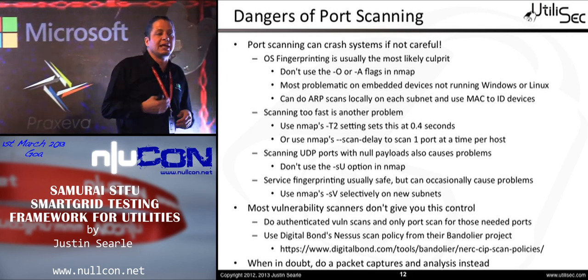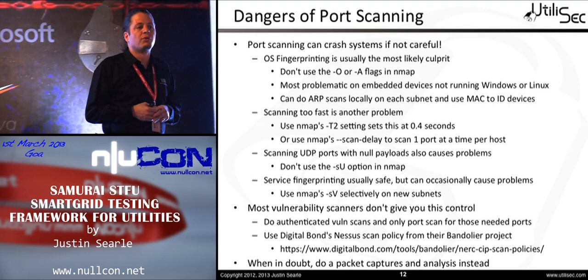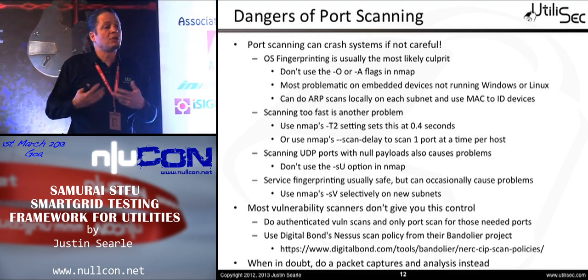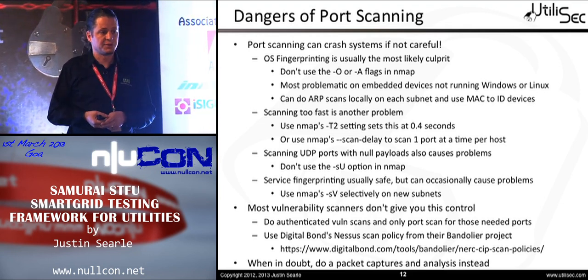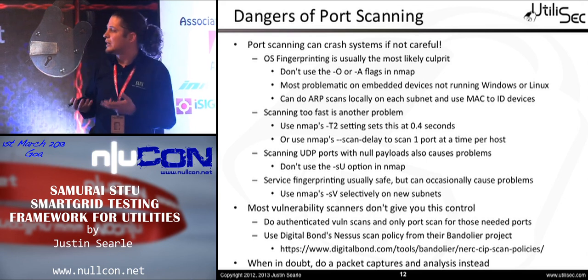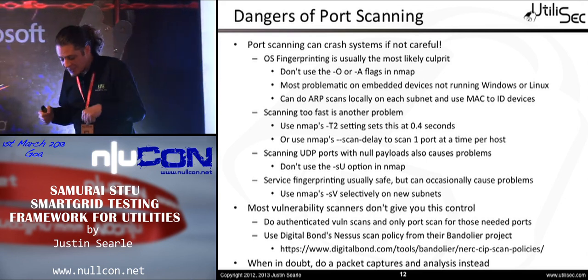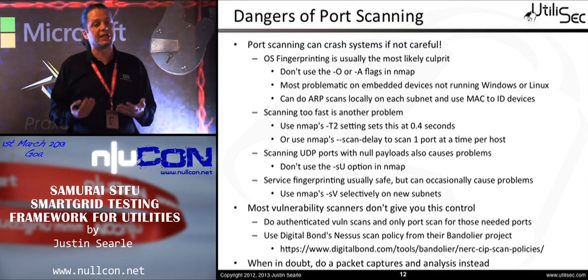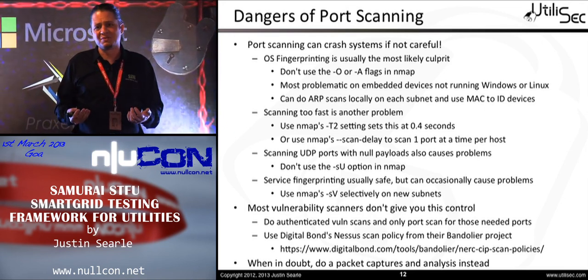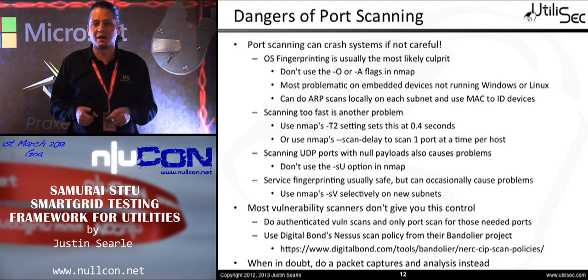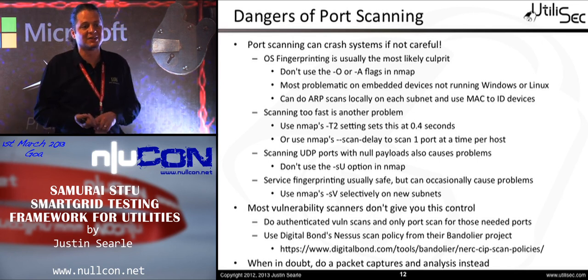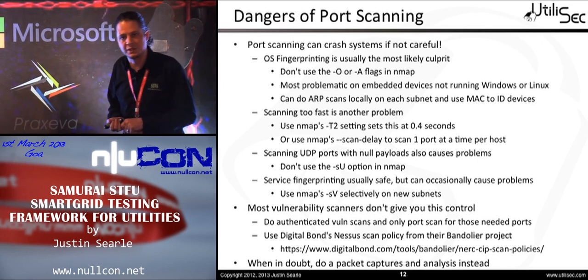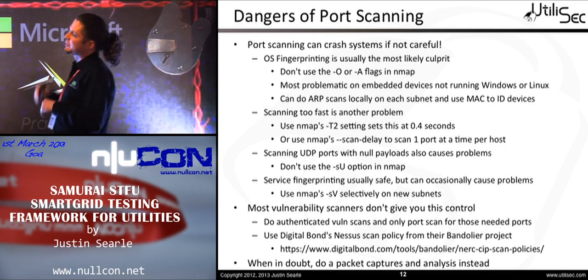We also try to provide contextual information for security professionals that may be new to working inside of control centers. Okay? Inside of the control networks, we have highly sensitive systems, as I had mentioned. A lot of these systems don't hold up to traditional testing. They don't even hold up to traditional IT queries and finding out what's there. Doing a basic Nmap scan, unfortunately, still knocks over many of these control systems, especially the older ones. Okay, so we try to provide some contextual knowledge.